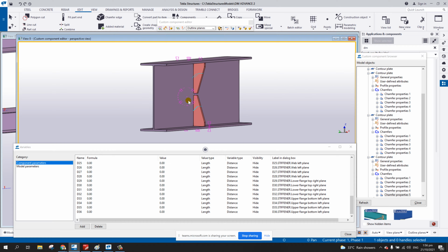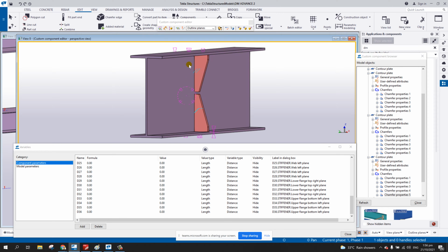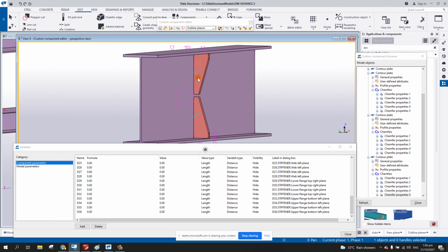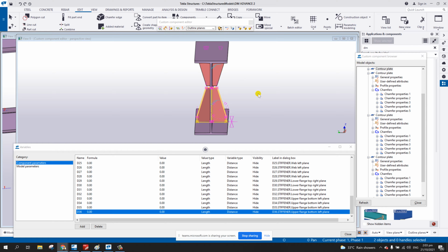Okay, now the reason why I bind that one to the outline of this beam, so that whatever the changes of the height and the width of the beam, then my stiffener will go along with that surface. Okay? Are we clear on that one? Okay, so kindly do that one now. Continue. We're still a long way to go.